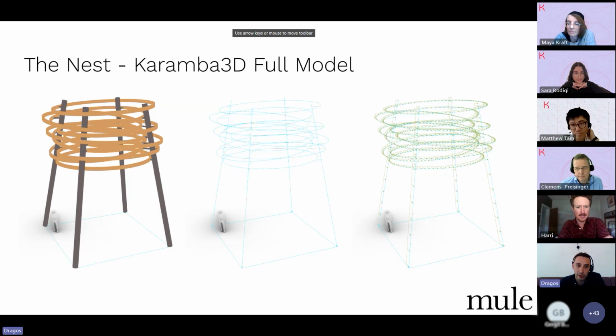It's worth mentioning that it's actually the wind load that is the governing situation here. It's quite a tall structure, around 10 meters tall, in a windy location by the port in Belfast. That was a big driver for everything that I'm going to talk about next. We developed all these things fully in Karamba as part of the modeling process.